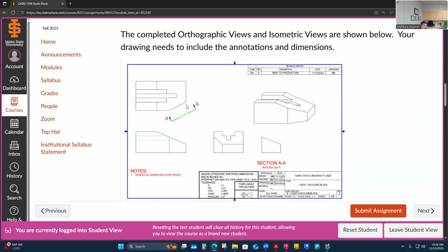I could dimension it here, but it would be an angled dimension, and we kind of avoid angled dimensions. Even though you may work in an industry where angled dimensions are totally fine, I'm just saying with ASME, we kind of avoid them. The only reason you need that is because maybe it's just a better detail on this rather than just pulling in a line dimension here. That is its true length that you're dimensioning here. And you really don't need the heights because this is a true height.